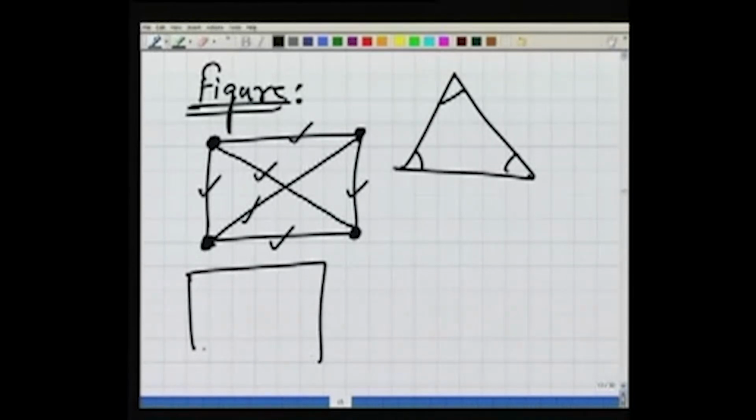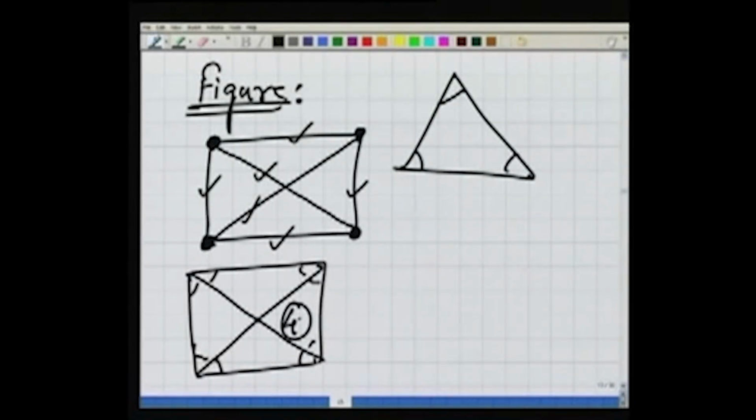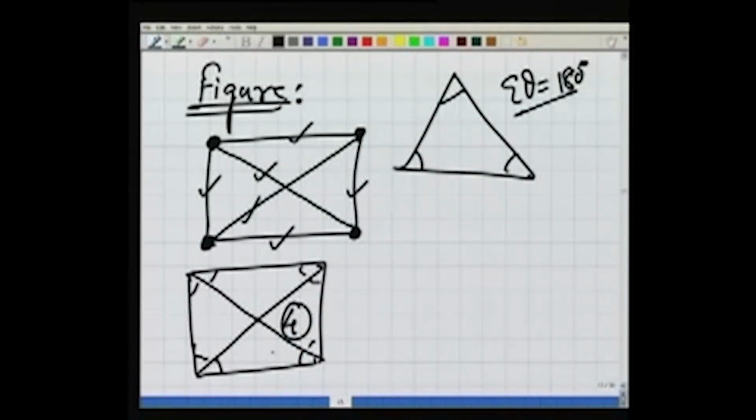One example: in triangulation, if we have a braced quadrilateral where you observe only these 8 angles, we have 4 conditions. We will talk about these conditions later on, but a condition here, in the case of a triangle, is that sigma theta should be 180 degrees. In a simple triangle there is one condition. So here we have 4 conditions in a braced quadrilateral.